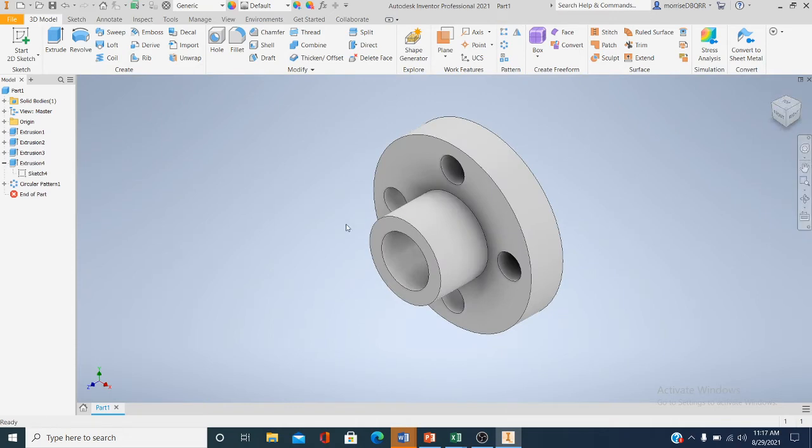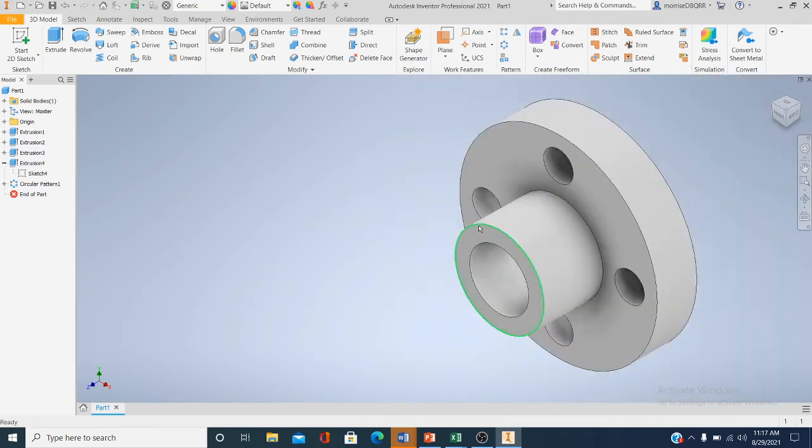But we have to put a chamfer here, and we're going to put a rounded edge here. So a chamfered edge is a beveled edge, and Mr. Morris, what's the point of a chamfer? To just basically reduce sharp edges. As you design things, when you become a designer, you want to eliminate sharp corners and sharp edges every time you have the opportunity, because it prevents a safety hazard for someone who's going to be handling the part.